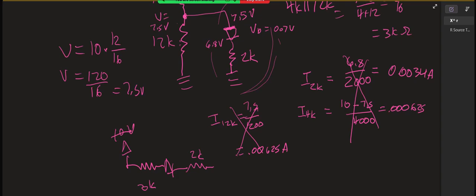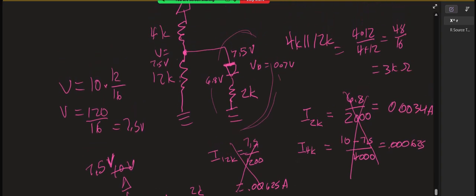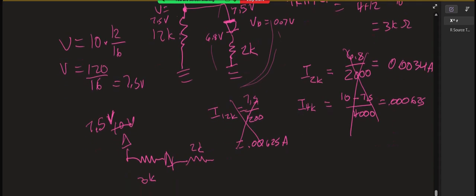The 10 volts changes to 7.5. Okay, yes. Why would the Thevenin analysis not include the 2K? Couldn't that be simplified with the 12K, or with the 3K that you got from the other part of the Thevenin, to make a 5K resistance for ground?